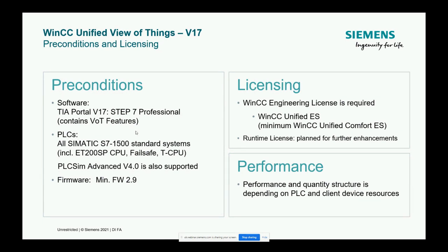We support all of the SIMATIC S7-1500 CPUs, from the standard controllers to the ET 200SP, failsafe, and the technology CPUs, and we also support PLCSIM Advanced version 4, which is the new release with version 17. As a minimum, we require firmware version 2.9, so you may need to update the firmware version.